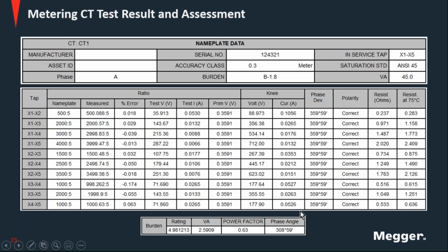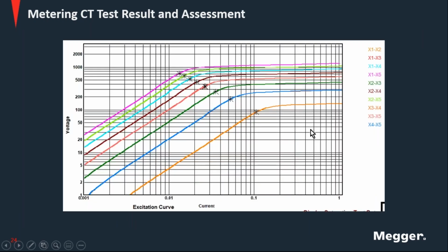In that other part, for small changes in voltage, you have huge changes in the excitation current. Well, what the security factor tells you is, for a particular overload, I don't know, 10 times, 20 times, 5 times the nominal current of the CT on the secondary, what is the cutoff point that you want on the error, right? And the error on the CT, as Volney showed over there, is the excitation current.